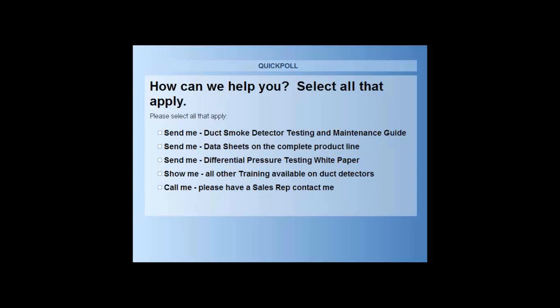What you always want to ensure is that your sampling tube goes at least 2/3 of the way across the ductwork if it doesn't go all the way through the other side. And you want to make sure the holes have an even distribution across the width of the duct. As long as you have that, you're not violating any sort of listing.